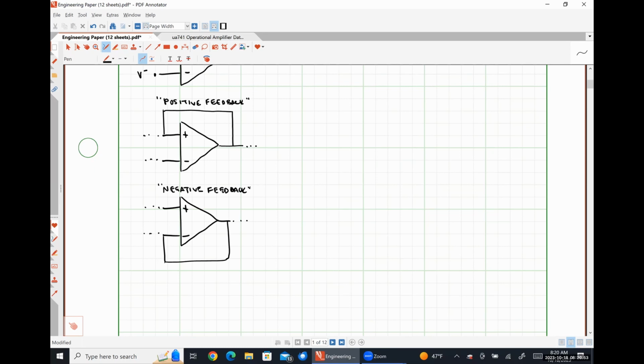By the end of Friday's lecture, we're going to see how op amps can be used to add voltage signals together, take the difference of voltage signals, scale voltage signals, and invert voltage signals, meaning just change their polarity or multiply by a factor of -1. We're also going to see how they can be used to integrate and differentiate signals. For instance, if you had a square wave and you wanted to make a triangular wave, you would use an integrator, because the integral of a rectangular pulse would be a triangular pulse, etc.